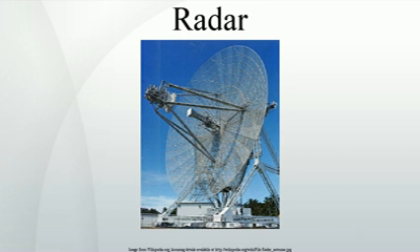Radar equation. The power P returning to the receiving antenna is given by the equation where Pt equals transmitter power, Gt equals gain of the transmitting antenna, Ar equals effective aperture, area, of the receiving antenna, σ equals radar cross-section, or scattering coefficient, of the target, F equals pattern propagation factor, Rt equals distance from the transmitter to the target, and Rr equals distance from the target to the receiver. In the common case where the transmitter and the receiver are at the same location, Rt equals Rr and the term Rt²Rr² can be replaced by R⁴, where R is the range.